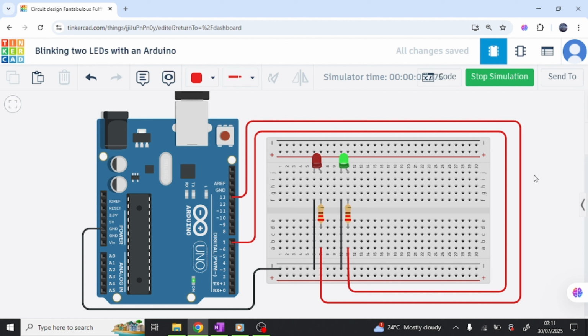Okay. So now, of course, what do you observe? Your observation: after spelling pinMode with a capital letter O, we had an error. After using "digital rights" and not spelling digitalWrite correctly, it refused to run. Now this, we are supposed to use if I was using a physical Arduino.